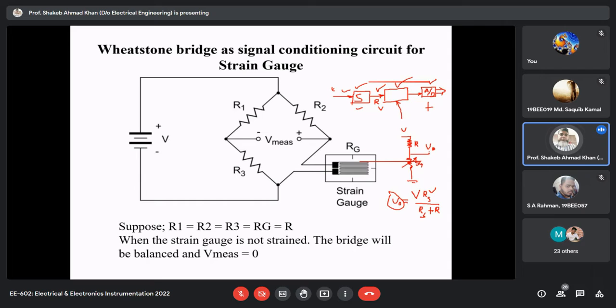So these intermediate stages, whatever we are doing to make our signal suitable for the next stage, are called signal conditioning. In this case, after the strain gauge, we are connecting this voltage divider circuit, which basically converts the resistance into voltage, and is a signal conditioning circuit. Now if your signal does not have the required amplitude, then we will amplify it. So this is called amplification.